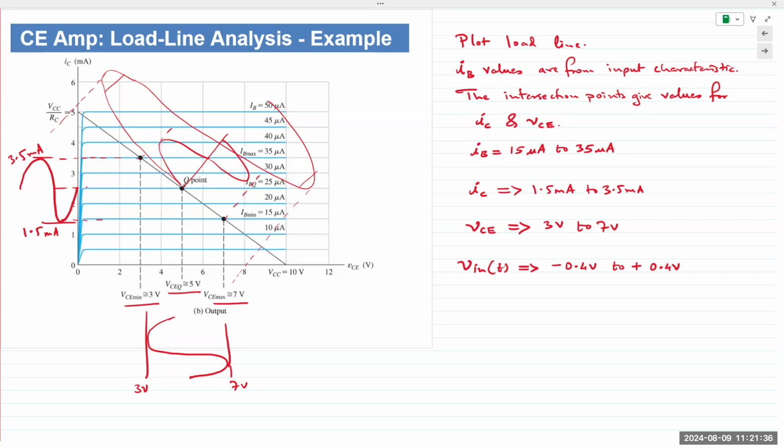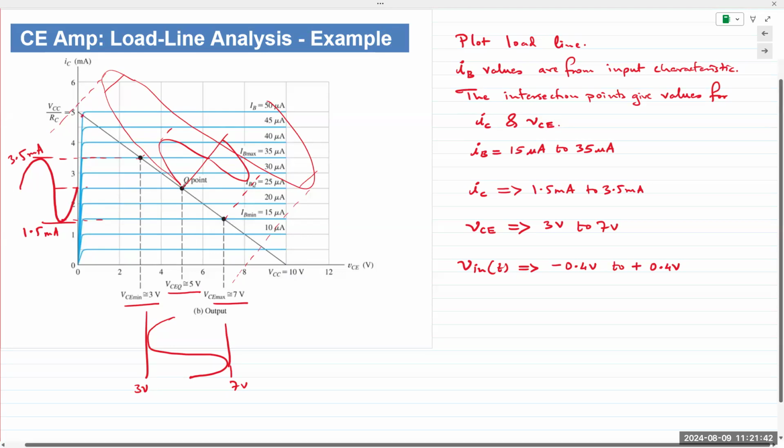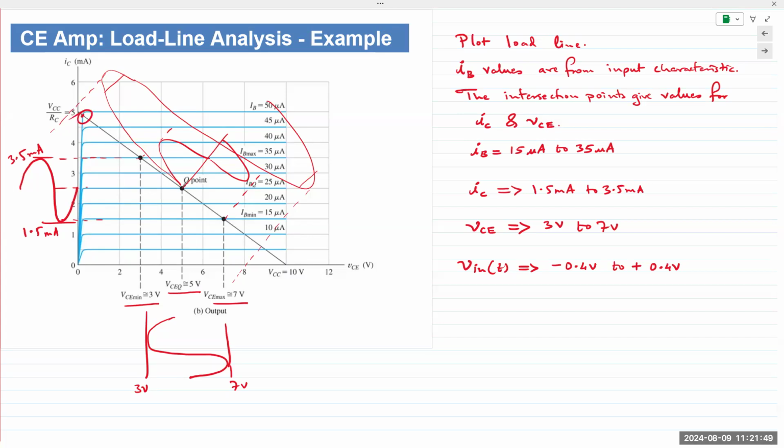So it would be somewhere over here. Different transistor, your Q point or center point is like right here. Even before you do anything, you just apply a little bit of positive V in, it's like in saturation. Does that make sense?